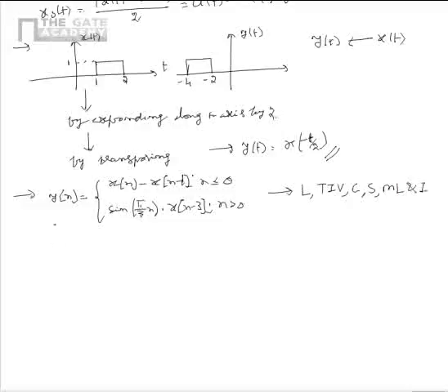We see that for the given system, the superposition principle is satisfied, so the system is linear. And also we see that for n less than or equal to 0, the input output relation is different from the IO relation for n greater than 0. From this we can say that the system is time variant. Here we see that the output at any instant depends on current and past inputs. So the system is causal, but the output depends on past inputs. The system has memory.